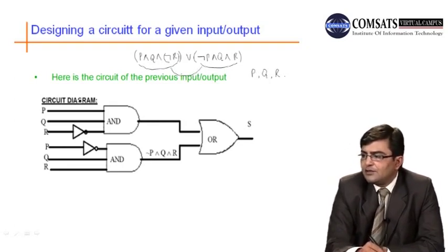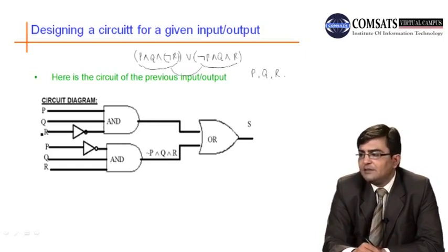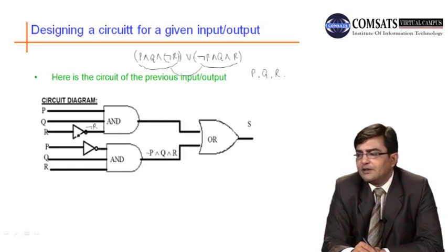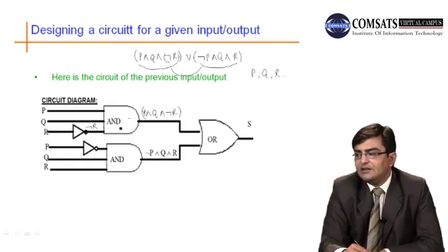and then we construct a logic gate for this expression, and then we connect both logic gates with each other. So to construct a circuit, we write P, Q, R. Basically P will go to the AND logic gate here, as we have P and Q. So Q is the input of this logic gate, and here we have not R. So we have written R and we have made a negation operator here, and the output of this negation operator, or NOT logic gate, is not R, and the input for this AND logic gate is P, Q, not R. So the output of this logic gate will be P and Q and not R, corresponding to the inputs P, Q and not R.